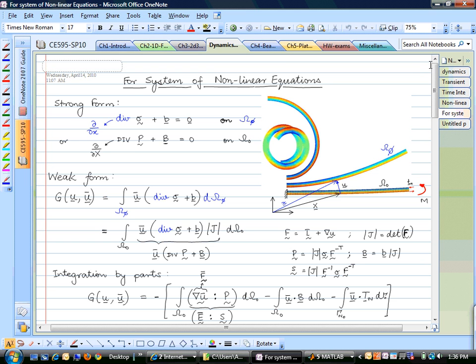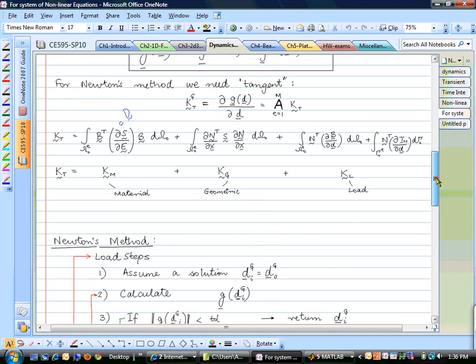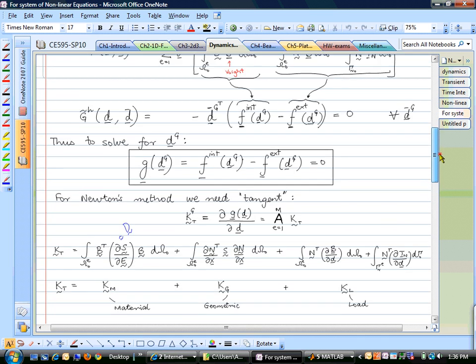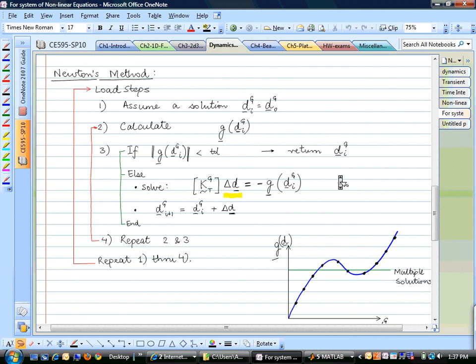So just to round out what we were talking about last time, we were talking about all these nonlinear problems, and I told you that for nonlinear problems, what you are usually trying to solve is a system of nonlinear equations that just looks like internal force minus external force is 0. And this is a vector equation. The most common method that we use to solve these types of equations is Newton's method.